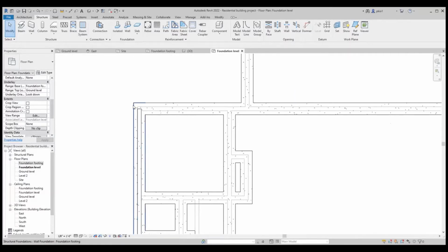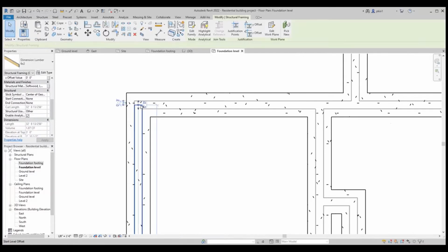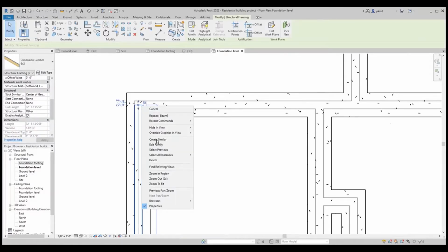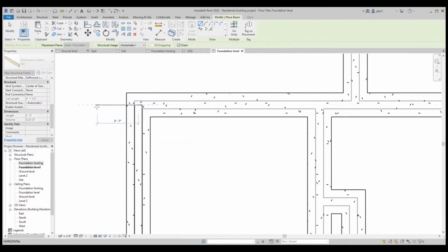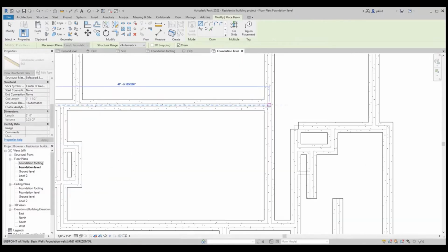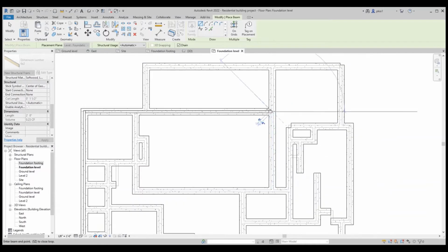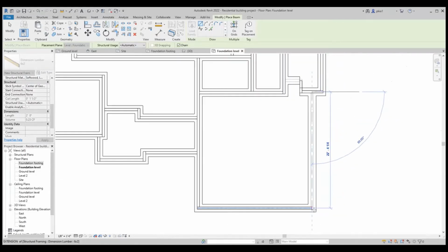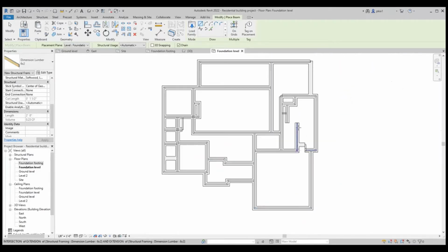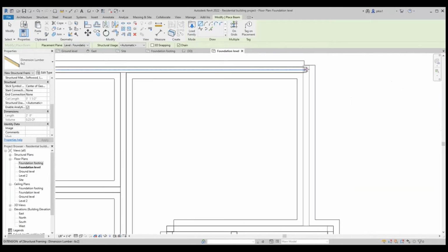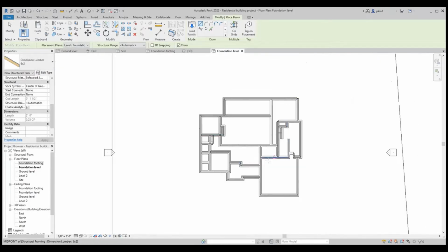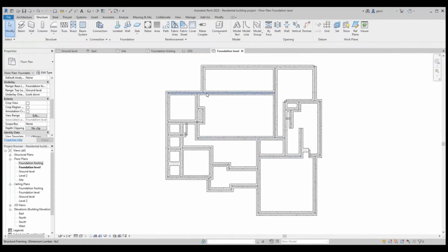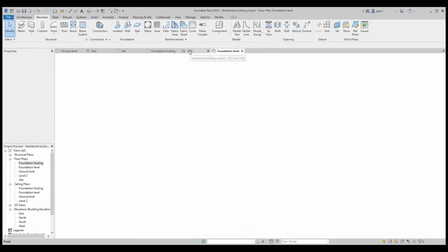In order to apply this seal plate all around this foundation, we'll select this seal plate and say create similar. I'll come over here and draw the seal plate. It helps to go in one direction and then another. So the triangle signifies the midpoint of any place, the triangle. And so after drawing the seal plates, we take a look at it in the 3D.